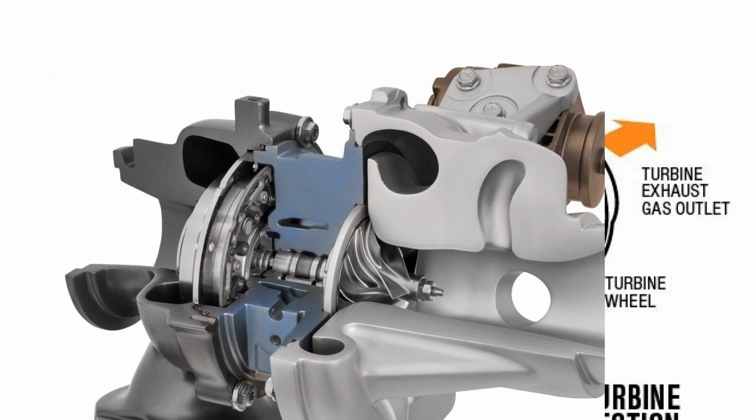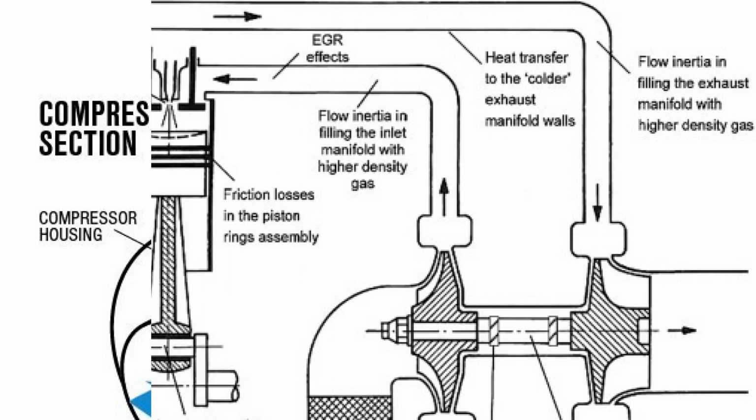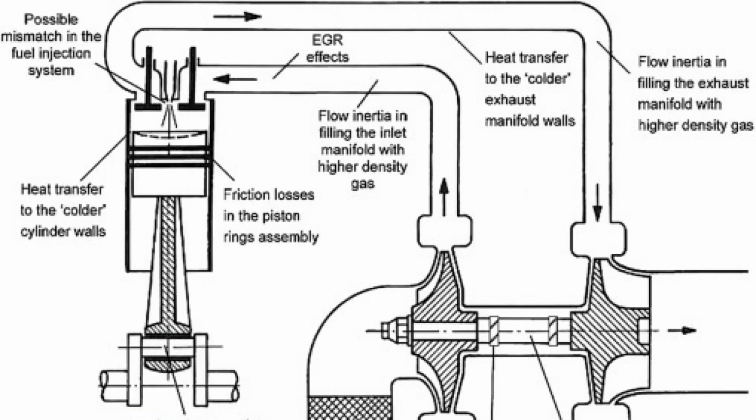System in section. The blades are arranged perpendicular to the radial lines to provide a narrow cross-section for the exhaust gas flow. This provides rapid boost and torque gain in the low engine speed zone. Stepped blade arrangement: large cross-section for exhaust gas flow. The same mode is used as an emergency mode when the self-diagnostic system registers incorrect system operation and there is no power to the solenoid valve.